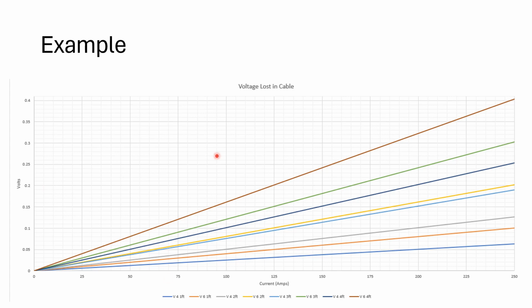Now, this was done using Ohm's law, or V equals IR, and you can see all of those here. I'm assuming a 12-volt battery in my calculations, but you have amps, and then you have the resistance of the cable, and that's given per cable. That was all those numbers in the previous slide. And this is the voltage drop. So, little example of how you can use that.